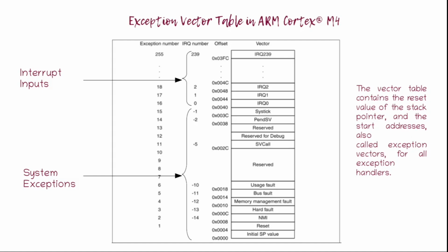That is not the case always, but it is possible. The Cortex M4 architecture ensures that such an approach is possible, in two ways: automatic saving of registers on interrupts, as we saw, and having only addresses mentioned here instead of jump instructions, because jump instructions would generally be in assembly.